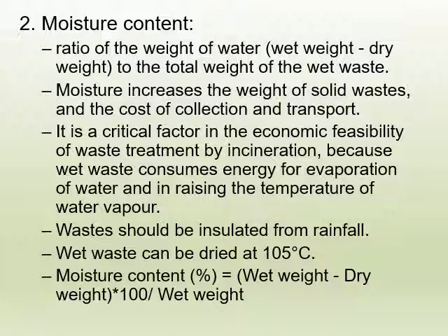Wet waste can be dried at 105 degrees Celsius. So moisture content, if we want to determine: weight of waste minus dry weight of waste, into 100, divided by weight of the waste.